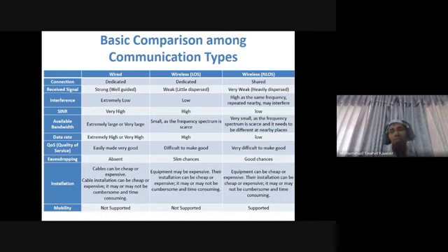Quality of service, again, will be easier to maintain for the wired case and LOS case. Eavesdropping, somebody else overhearing your signal. In the wired case, they cannot, since you have dedicated communication within the wire. In the LOS case, the signal is in the air, so there are chances, but slim chances because your power is confined within the region. But in the non-LOS case, you are dispersing your signal. You're leaving it open to everybody. So unless you have some special measure, everybody can hear the signal and retrieve the bits. But we'll later address these things.